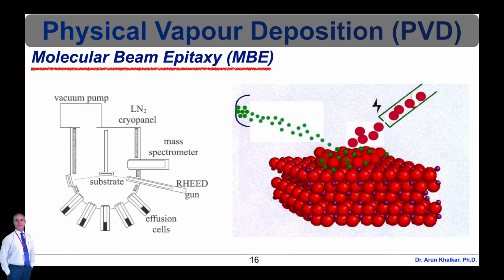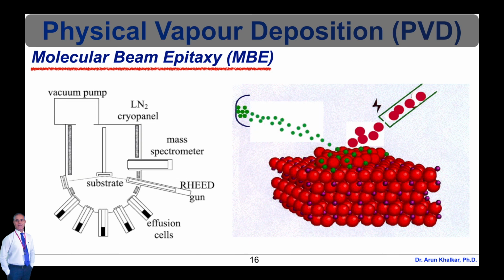Now let's see the epitaxial growth. As shown in this diagram, due to the interaction of molecular or atomic beams on the surface of a heated crystalline substrate, the solid source materials sublimate. They provide an angular distribution of atoms or molecules in a beam. The substrate is heated to the necessary temperature. The gaseous elements then condense on the substrate, where they may react with each other. Atoms on a clean surface are free to move until finding the correct position in the crystal lattice to bond. Growth occurs at the step edges formed, as there are more binding forces at an edge.